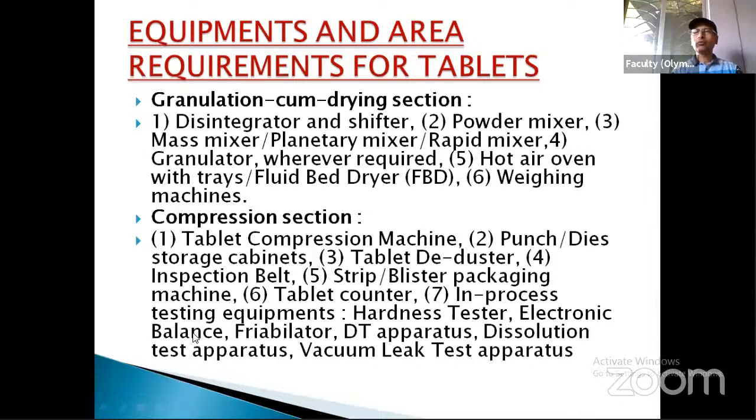You will get how much powder is coming out from the tablet. It obviously depends. One of the factors of this friability test is hardness. If hardness is less, a greater amount of powder will go out from the tablet, and that is why you have to correct the hardness properly. You have to adjust the machine accordingly.